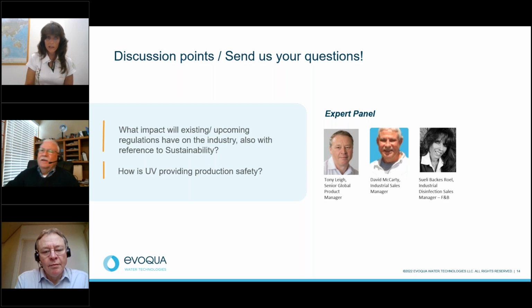Yes, absolutely. As Tony put up on one of the slides about UV dosing, Pseudomonas is a very common, ubiquitous microorganism, often found in water supplies. UV is very effective in inactivating Pseudomonas and most of those types of organisms. So yes, that's a great application of putting UV in. It's somewhere around 30 to 40 millijoule dose that would be needed.